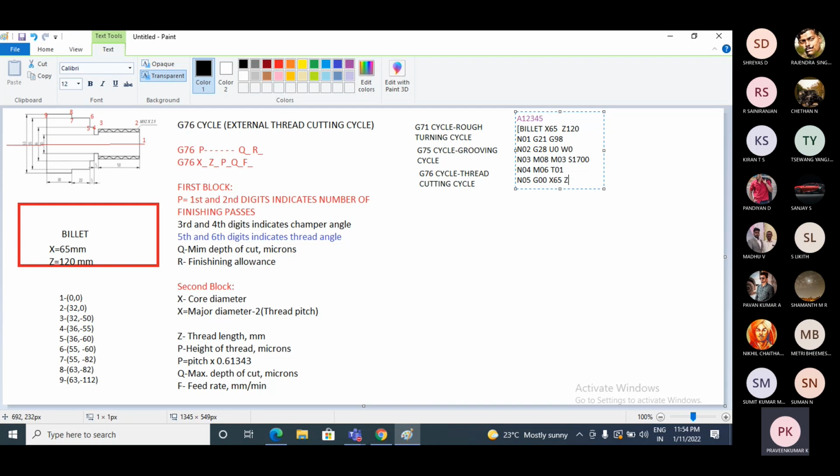Let us take 1 mm, or 0 is also correct, 1 mm is also correct. Even if you are working in front of a CNC machine, a programmer should generally maintain a small gap between the tool tip and the work surface before writing any part program. Anyhow, you are doing simulation kind of work, so even if the tool tip touches the work surface, it won't affect the part program, the tool geometry, or the workpiece geometry. Okay, so this is a rapid movement of the tool.